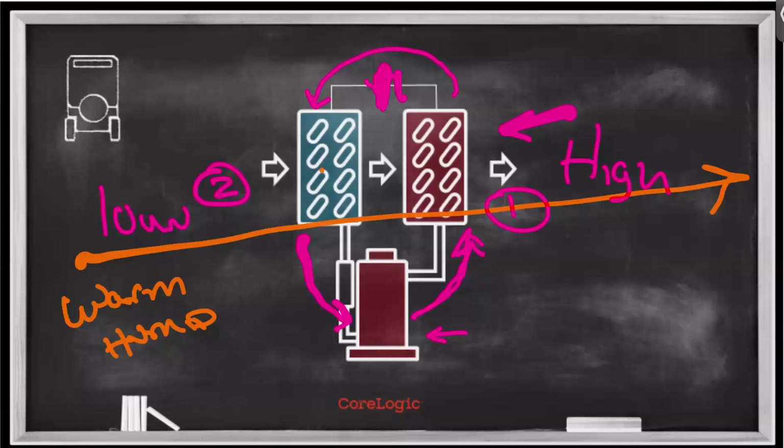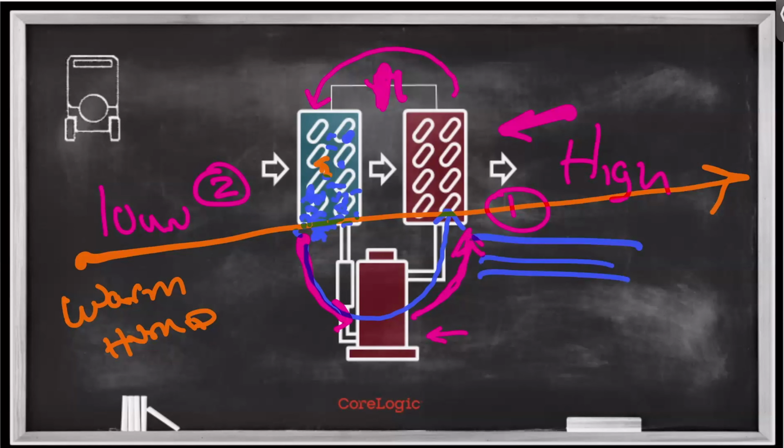As that moisture sweats onto this surface and collects on this coil, the refrigerant dehumidifier is absorbing the energy not from the sensible temperature anymore. It's taking the energy from the moisture. And all of that energy from the moisture that's condensing on the coil gets pumped over here to the second side and gets compressed as sensible heat. And then leaving the dehumidifier on the backside, all of that sensible heat is measured as a temperature rise.